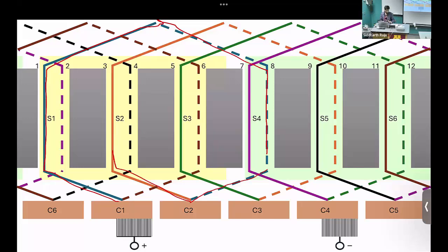All right, so this is a coil diagram, not a winding, not a single wire diagram. So when I represent this coil, that means if there are 10 windings in the slot with a single loop forming a single coil, that whole thing is just represented by 1 line. So this one is a conductor going in the forward direction, coming from the bottom slot coming up. This is a conductor coming from the top going down. So that's what makes it double layer.